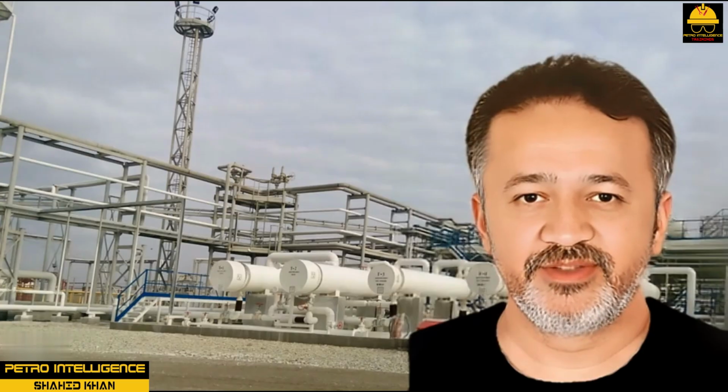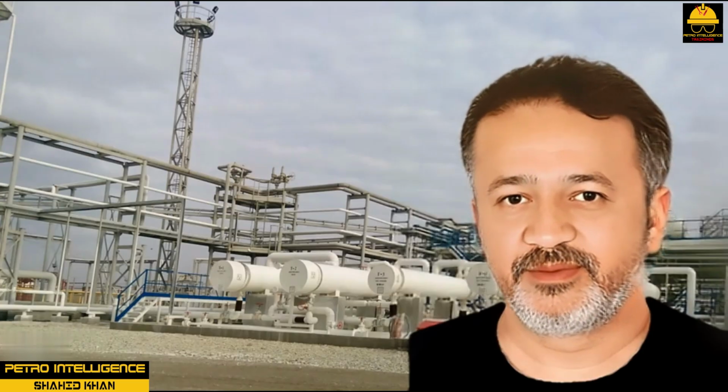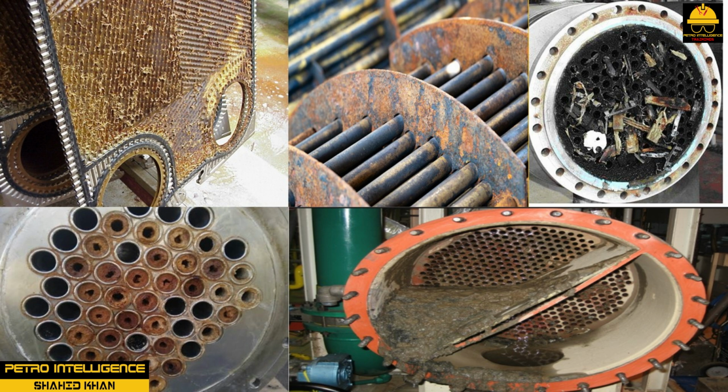Heat exchanger effectiveness and common problems. The design of an exchanger usually dictates how effectively it can transfer heat energy. Fouling is one problem that stops an exchanger's ability to transfer heat. During continual service, heat exchangers do not remain clean. Dirt, scale, and process deposits combine with heat to form restrictions inside an exchanger. These deposits on the walls of the exchanger resist the flow that tends to remove heat and stop heat conduction by insulating the inner walls.